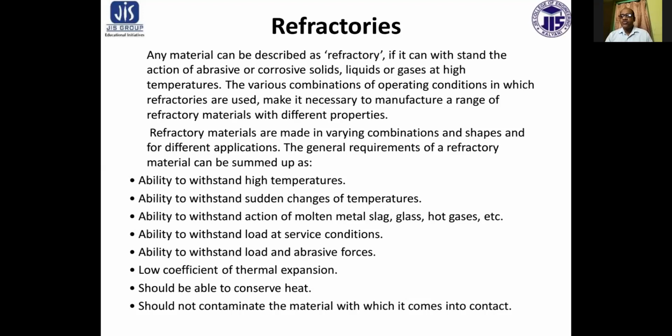The general requirements of a refractory material can be summed up as its ability to withstand high temperatures, sudden changes of temperature, the action of molten metal, slag, glass, hot gases, etc., and load at surface condition and abrasive forces.